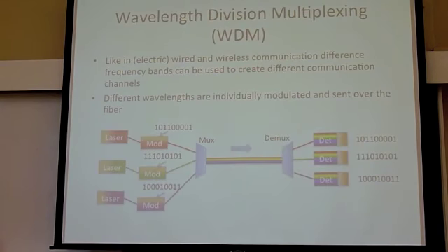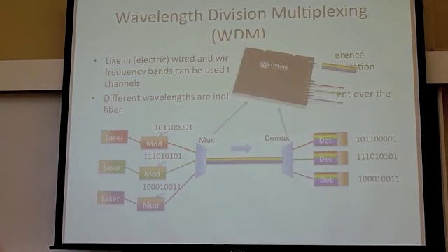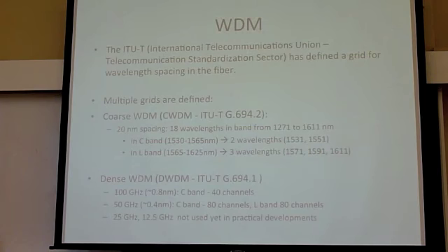So when you use multiplexing, most WDM, WDM means you have lasers at different frequencies, you modulate them, multiplex them, you put them together, and they all go on the same fiber. The multiplexers are passive components, and then you get more signals, so basically just putting more signals together on one fiber. That's an example of how one of them looks like.